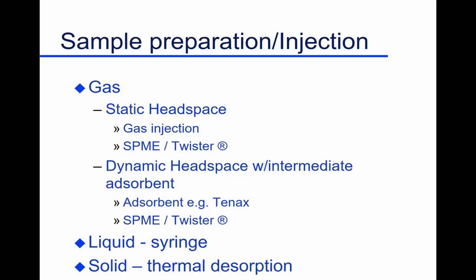It's called static headspace. It's an equilibrium. There's no motion, no airflow, nothing. Just close it in a container, allow it to come to equilibrium, sample it, and do your analysis. So you can actually directly sample. But we can do some extraction too, some concentration. These are a couple techniques that you'll see.